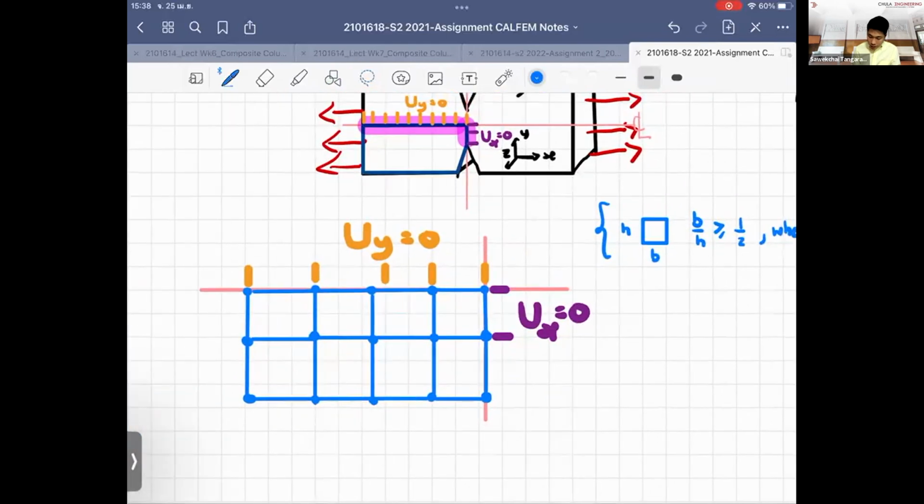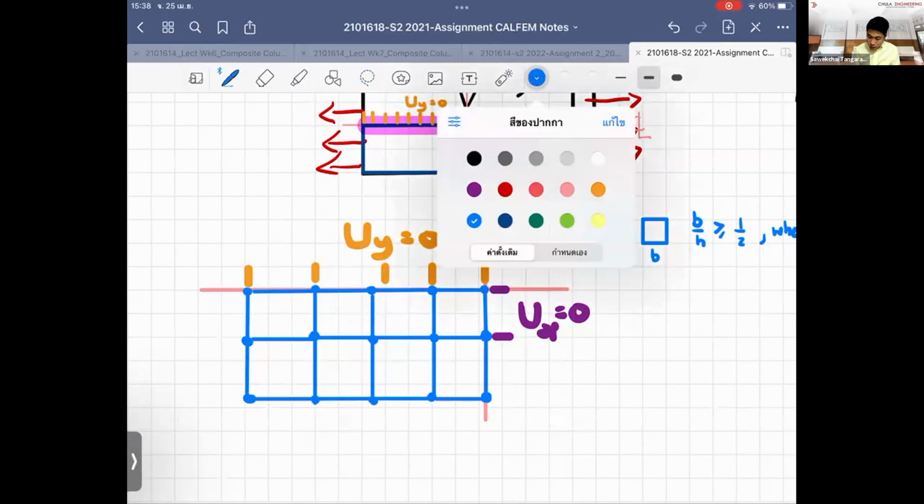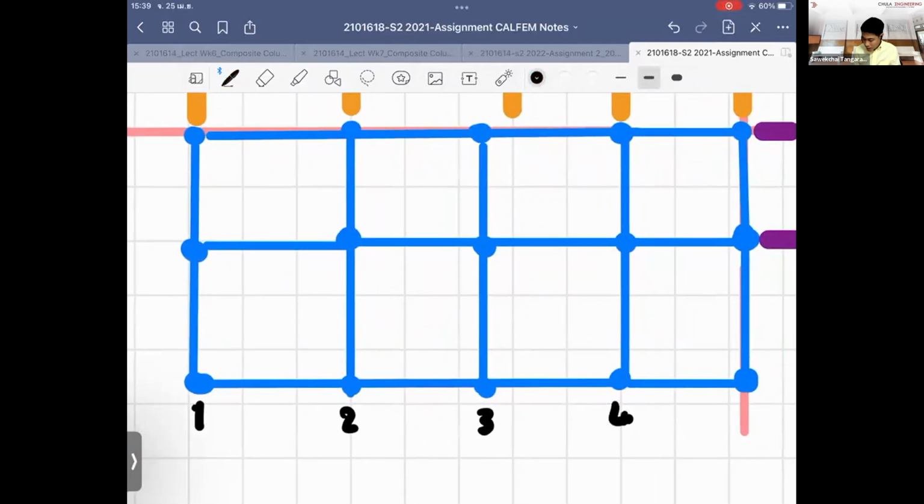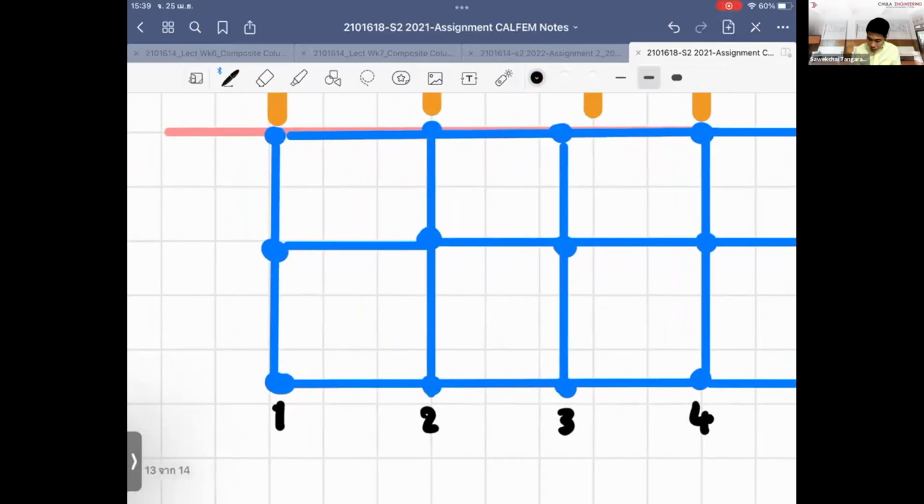And we have already allocated the boundary conditions. And what you do next, you have to put in the degrees of freedom. The rest of it is similar to what you did before, which is that you allocate the node numbers. I normally put them in order, starting from the rows, because later on I can see the series of them.